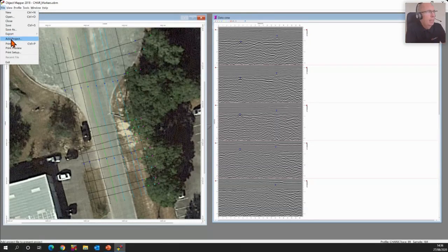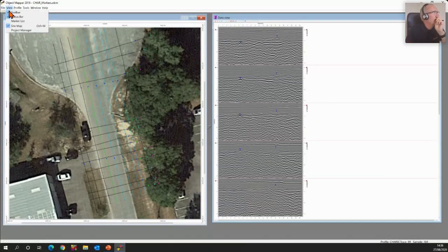So if we've got the baseline projects, so I've opened up one baseline project, and let's say it's the X baseline. I want to add the Y baseline, a secondary project, second baseline. Then you can click the Add Project option. It will ask you if you want to continue. Yes, it's going to change the name, and you will then go and find your second baseline in a different folder, second project, and then you can click Go or OK to that, and then it will add the two baselines together. You end up with two baselines. I can take a quick look at that. I think I've got one.